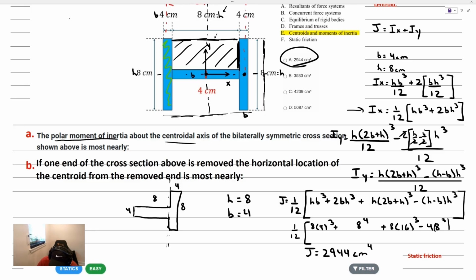So this is more of a conceptual question. Some people might place the centroid right here, right? Because the areas are equal. We're not looking for equal areas. We're looking for equal moment of areas. So while their areas are equal, the product of the area and distance is not, right? And that's what we're looking for at the centroid of the body here.